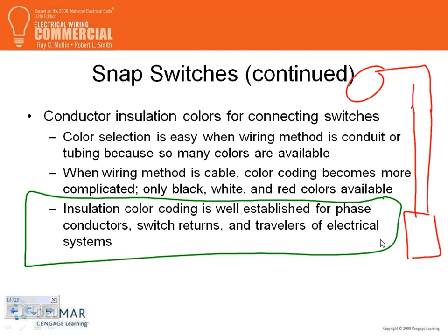My conduit is coming directly to my light, and these are conduits, remember. Then I bring my hot here, here's my switch, break the switch, and bring my other conductor, look at the colors, all the way to the light. This is hot 1 or phase 1, and it will land on my light, and my neutral is landing here. So that's how you do it in a conduit, because you can pull color-coded conductors.